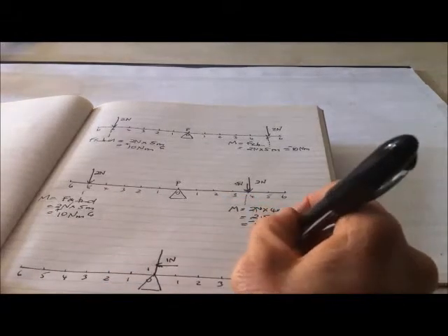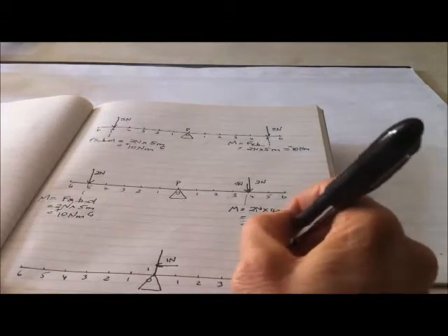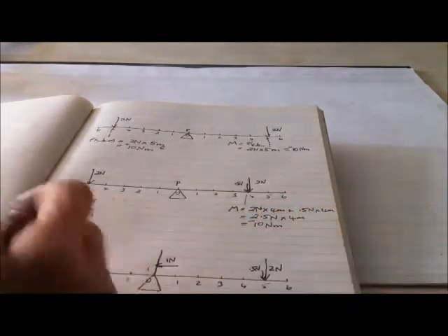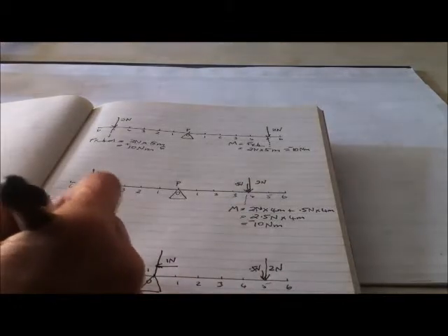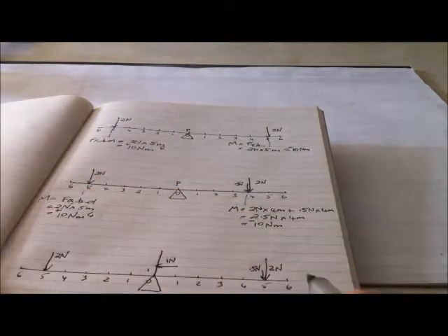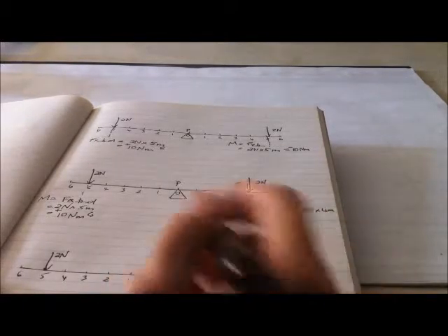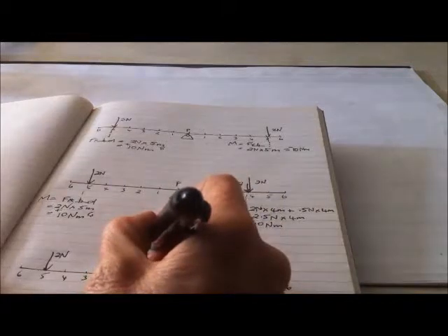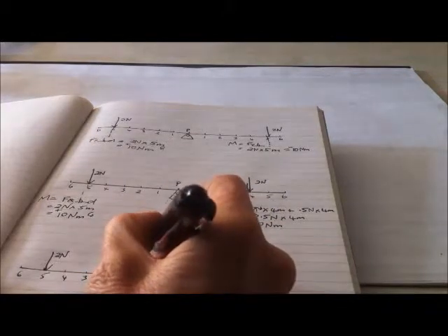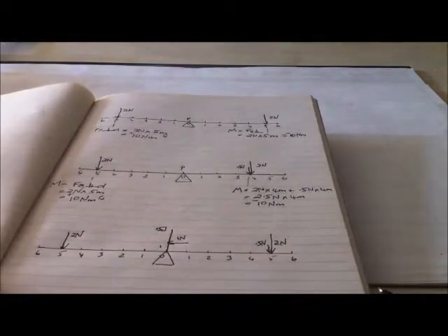We'll keep our 2 and our 0.5 newtons here, we'll keep our 2 newtons here, but now we've got an extra force happening down there. Let's say that this beam itself weighs 0.5 of a Newton. So how do we write the equations for that system? Stop the video and have a go.